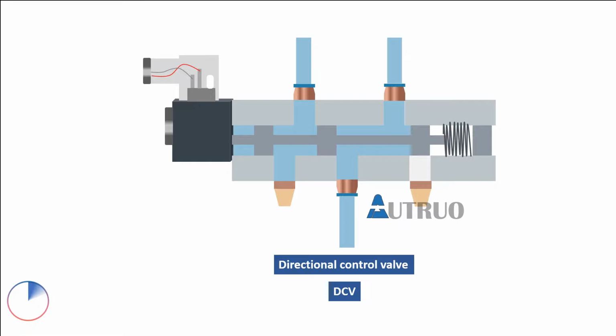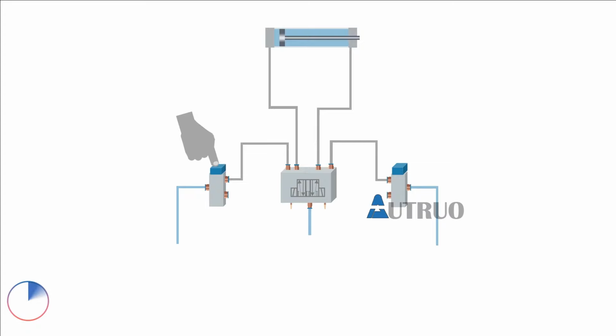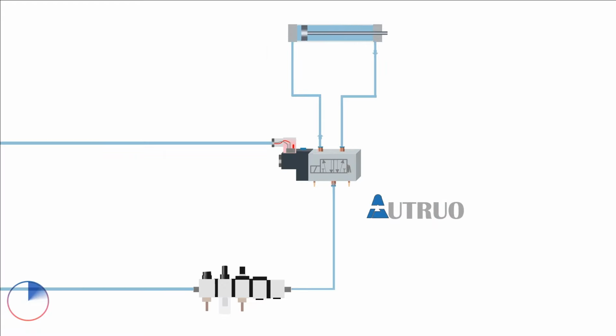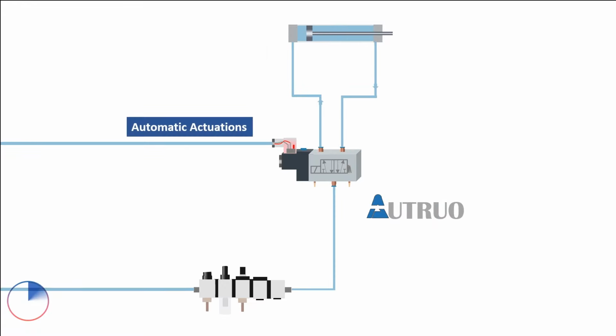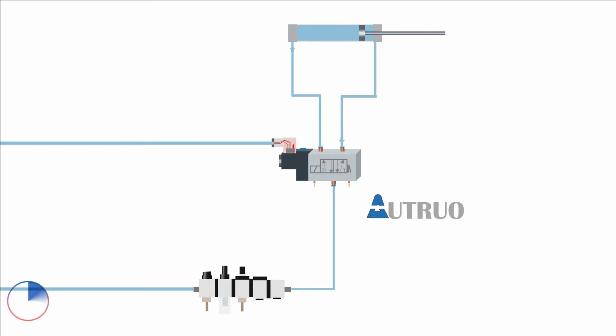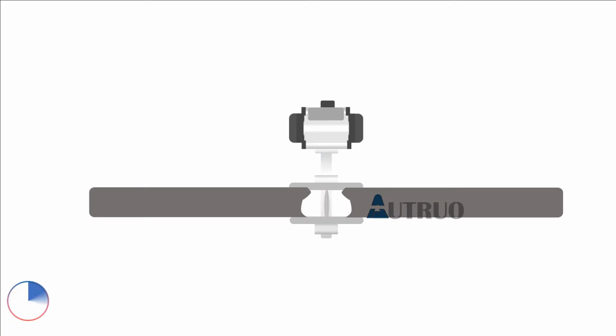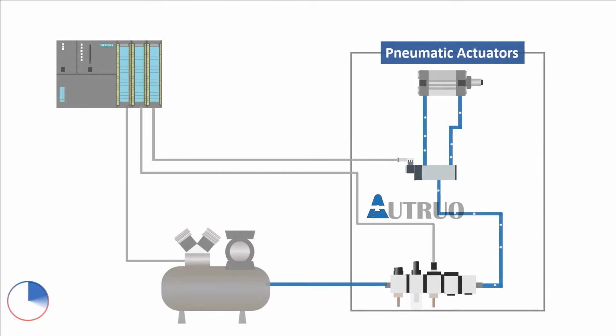Directional control valves can be actuated by human input, that is, when the push button is physically actuated or triggered, or through signals coming from the PLC or DCS. The actuated valve will produce a peculiar movement of the cylinder with respect to the port that has been actuated. The cylinder can further be used to regulate or manipulate the flows of gas, fluids, oils and steam in an industrial setup. On the one hand, valves are a critical part of the control loop system.